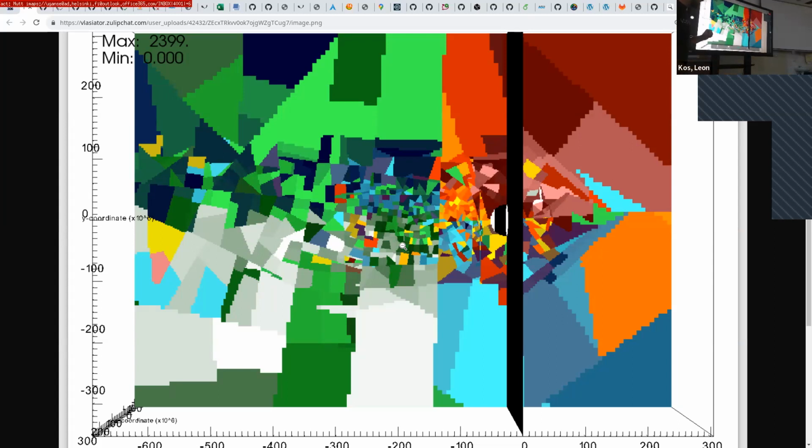So that turned out now to be even more efficient load balancing. For us, it's a 30% performance improvement that we got simply by trying this out. We had tried this 10 years ago, forgotten about it, and then tried it again. And this is now definitely something we want to put into our regular testing, because as the physical simulation and the physical features that we're simulating change, the ideal load balancing algorithm also has additional trade-offs. And here you can see, since these are now actually straight lines, of course, with stair steps, you don't have issues with the pencilization, you just build the pencils as they come.